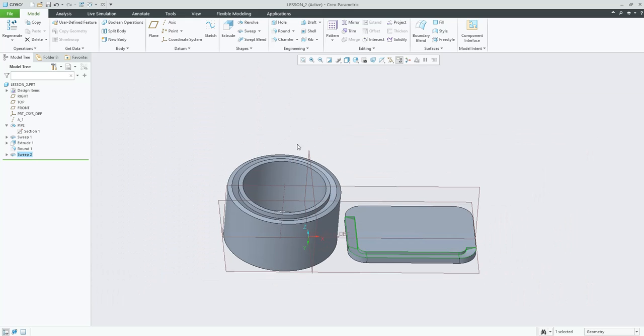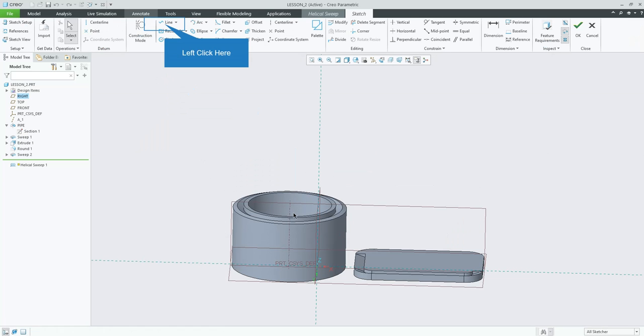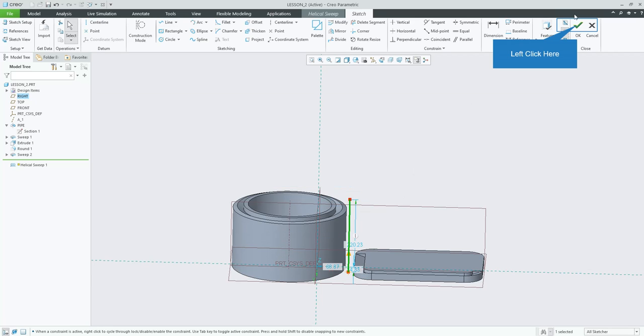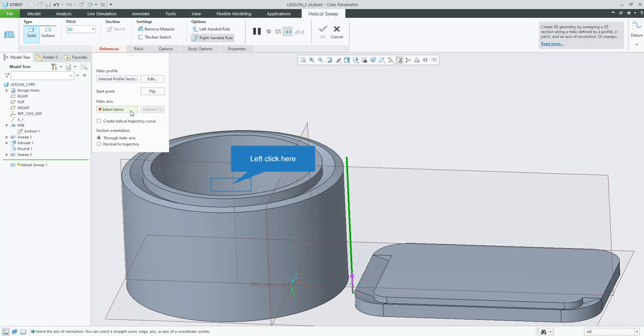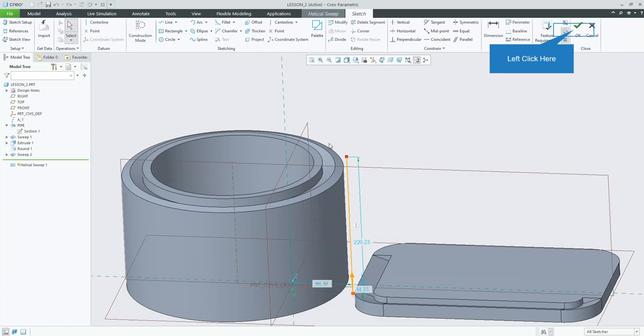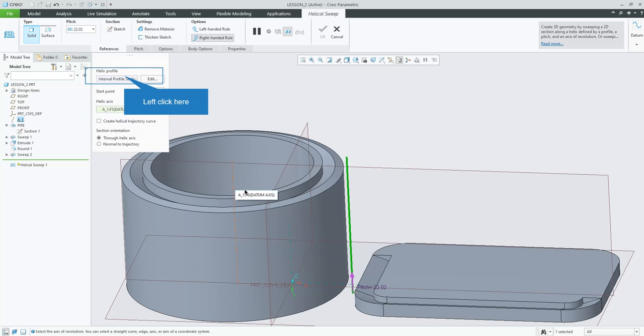So, the other sweeps are helical sweeps. Helical sweeps are pretty neat. You can basically design threads with those. You do a sketch, draw a line. That becomes how far it's going to go around there. And then you design a helical axis. So it's helical profile, edit, do your line, just a vertical line or a horizontal line, your axis of revolution,